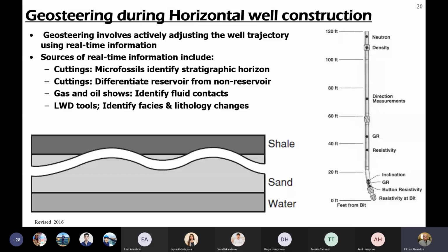In the horizontal case, if the water comes here and you shut off this part, this water will go through, because it's lateral, horizontal flow, and will spread in the other direction and easily reach the wellbore again. So you have to do water shutoff in the other zones, and this means more zones are cut off from the inflow from the production.